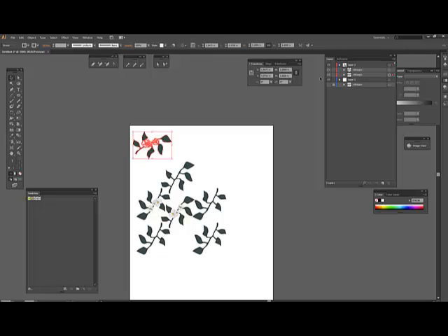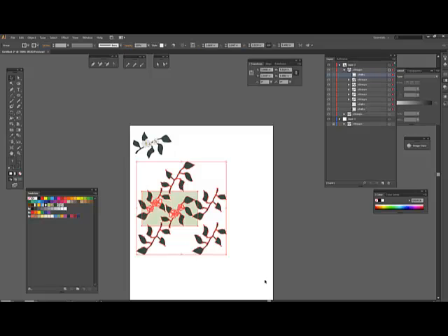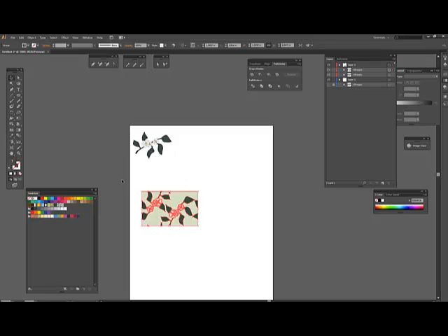So you open it up on the layer palette, find out where that is, and you get that unstroked, unfilled box in the back, and you do Control-C, Control-F twice. And then you move one of those boxes up to the front because that's going to be used for cropping. Then you want to put a color in the background. Okay, once you have your color in, then you have to work on your cropping.